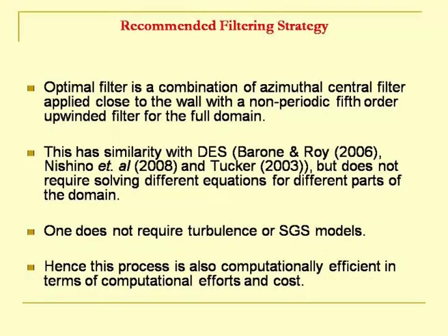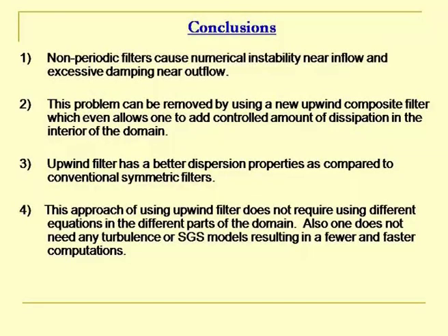So, this is a very good tool for one to learn and use it imaginatively, and you could also note that whenever you use non-periodic filter, you still have the problem of numerical instability near inflow and excessive damping near outflow. This has to be investigated, analyzed, and sorted out upfront. So, that can be worked out by using Upwind composite filter, which actually even allows you to add controlled dissipation in the interior.